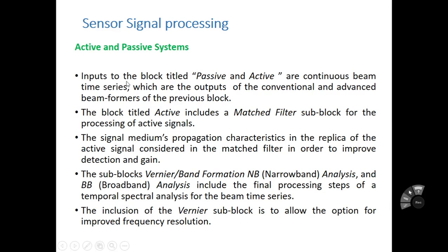The input to the block titled passive and active or continuous beam time series are the outputs of the conventional and advanced beamformers of the previous block. The block titled active includes a matched filter subblock for the processing of the active signal.